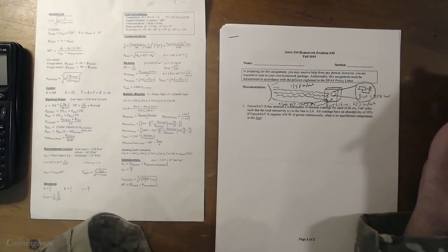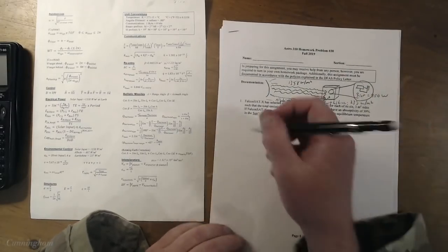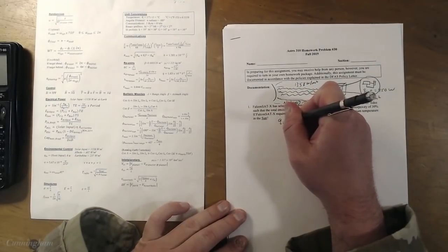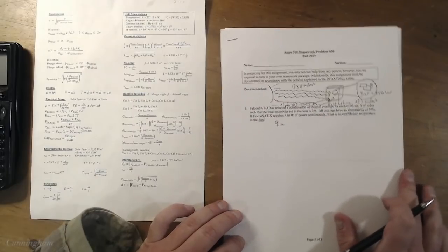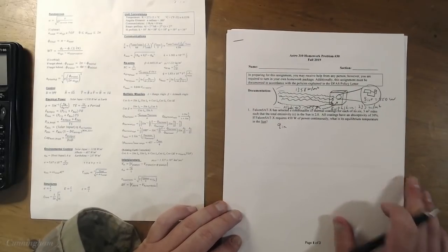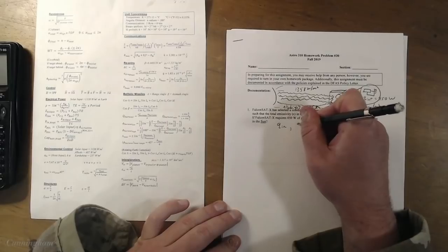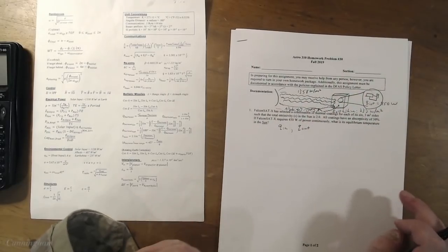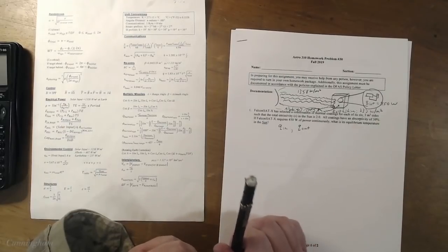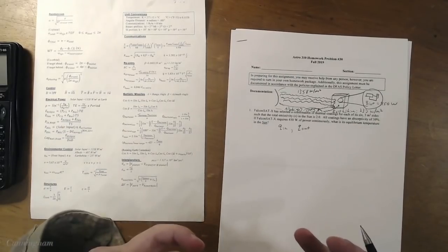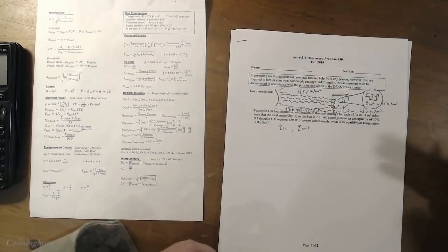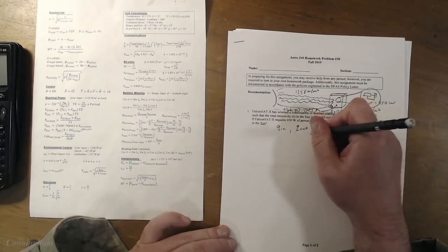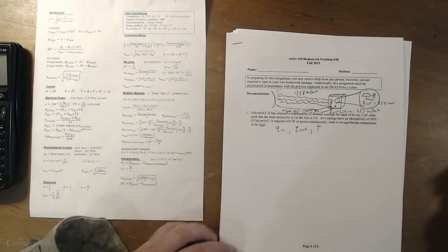So, well, that said, what we need to do first is calculate what our Q in is, how much heat is actually coming into FalconSat based on how big it is and if it's in the sun or not. Then we're going to calculate our Q out, which is the amount of total heat the satellite has to manage. Basically, all that does is account for all the heat coming from the sun and the Earth, and then add in the internal electronics and the heat that they're generating. That will give us the temperature.